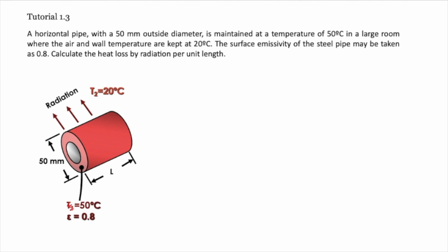So again, I'm going to change the summation of temperature. T1 becomes Ts, surface temperature, and the ambient temperature is T infinity. Okay, for radiation, you need to change the temperature from degree C into Kelvin.